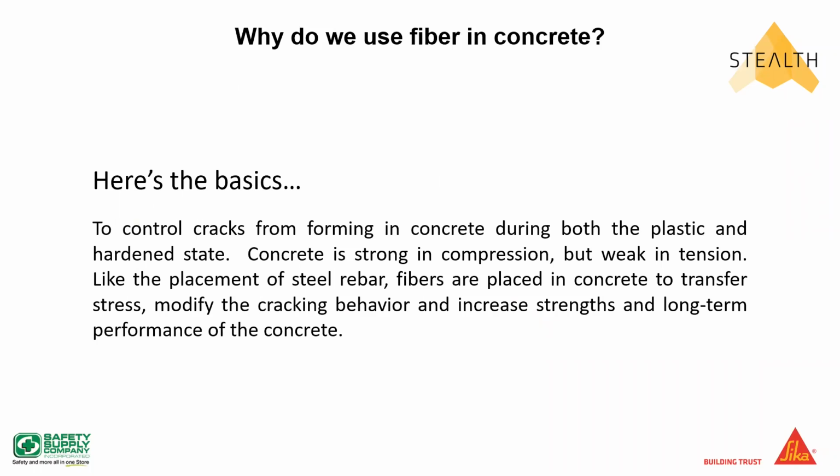So why do we use fiber in concrete? What's the purpose of using fiber in concrete? I think the best thing to say is to control the cracking, whether it's early age cracking from plastic shrinkage, temperature shrinkage cracks at the surface, or drying shrinkage and things like that as the concrete cures and as the concrete sits there for years. So we're going to talk a little bit about all of this, but mainly, why we use fiber in concrete, we want to control the cracking.